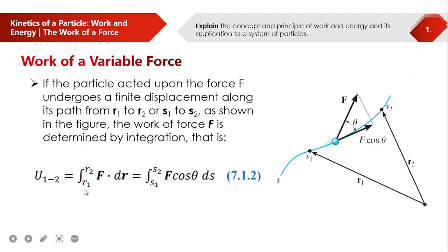Okay? So, if your force again is variable, you can compute your work using integration. This is U from 1 to 2 is equal to the integral of F dr from r sub 1 to r sub 2, or equal to the integral of F cosine theta ds from s sub 1 to s sub 2.